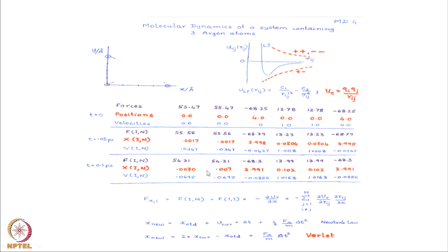And an important point I want to make here, what are the units we are using in this particular simulation program. Usually we use time in picoseconds, distance in angstroms, this is a standard practice. So, if you use time in picoseconds and distance in angstroms, the units of the force will be 10 joule per mole divided by angstrom.